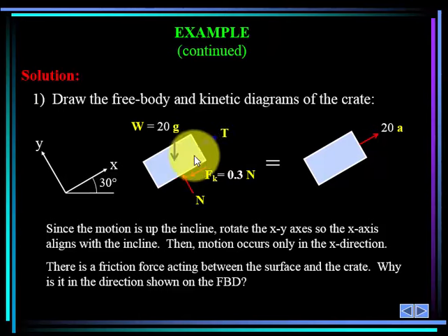And so the vertical, the y direction component in this case would be the cosine term. And let's just check that. What would the weight force be if our slope went to 0? Cosine would go to 1 when angle goes to 0. So the y direction force of gravity is the cosine term.